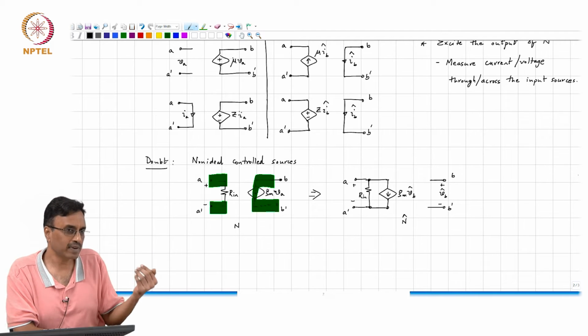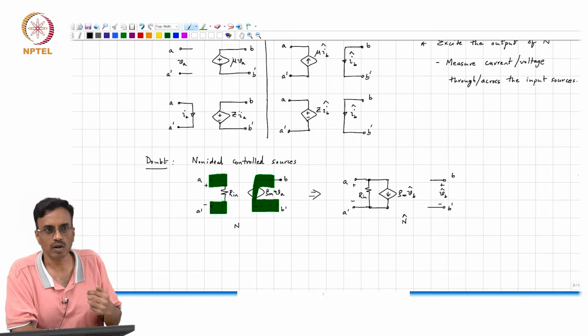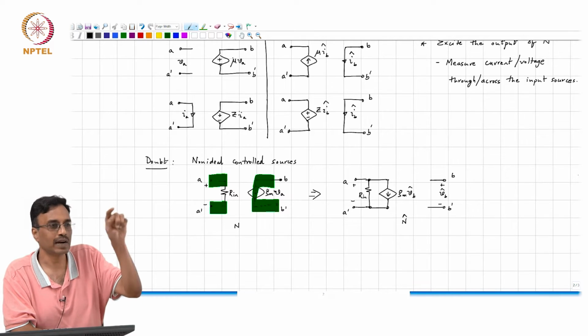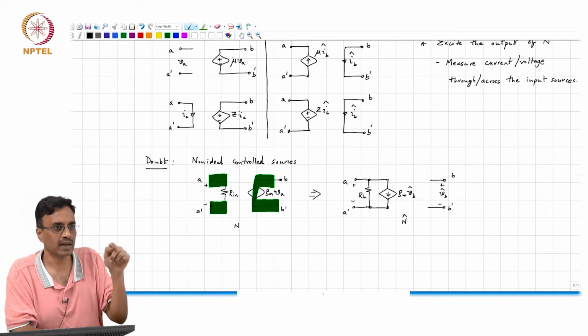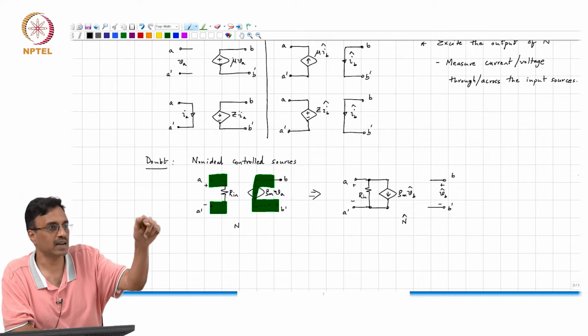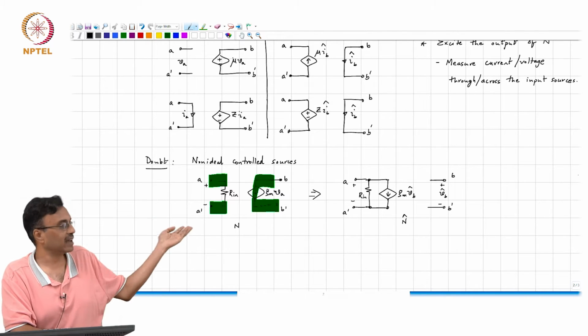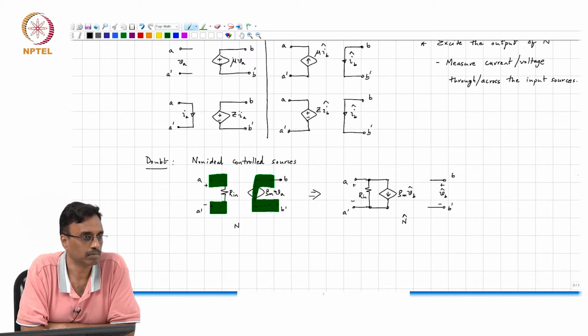Okay. The transfer function analysis is the same thing done upside down. You choose the output port, and you can click on any independent source inside the network, and it will show you the frequency response from that independent source to the single output, and that's done again using the inter-reciprocal, right?